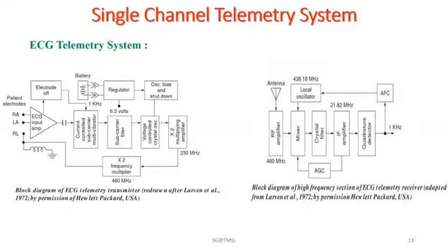It also provides 60 decibels of rejection for signals 13 kilohertz from the center frequency. An IF amplifier is there, which provides the requisite gain and operates as an automatic gain control amplifier that reduces the mixer gain under strong signal conditions to avoid overloading.